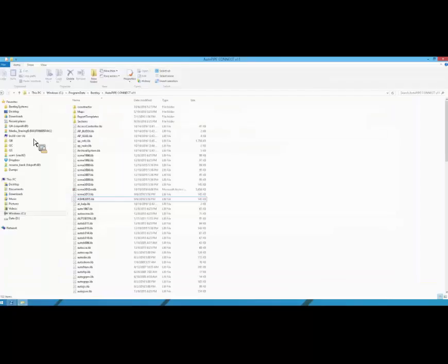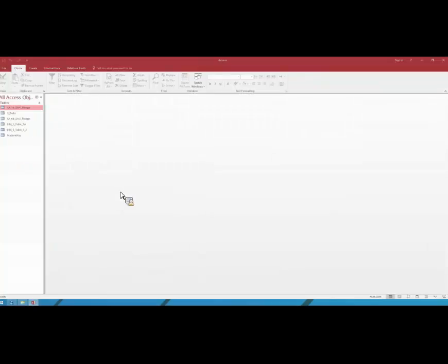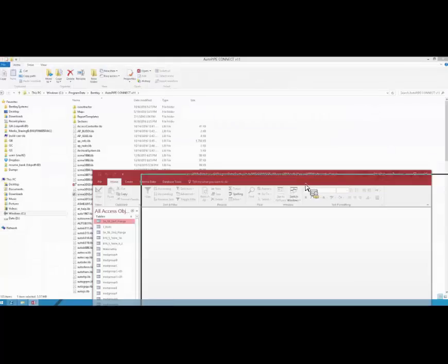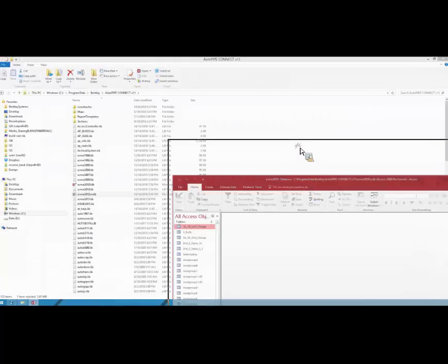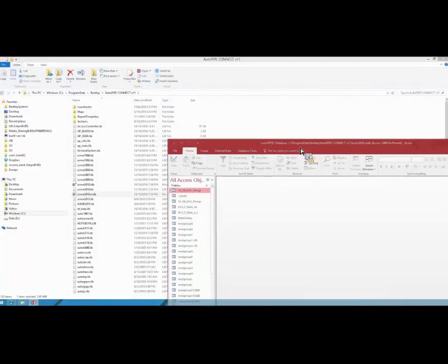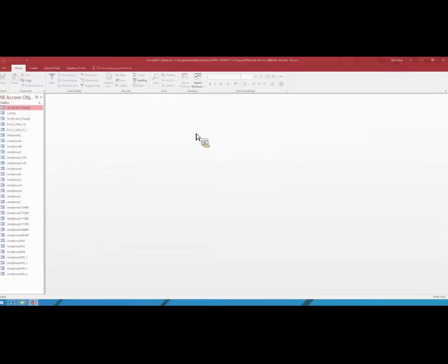I will really quickly jump on to the customization. We have the flange database available along with the AutoPIPE installation. That goes into the program data, Bentley, and then the version of the program that you're using, and it's labeled as ASME2010.mdb.